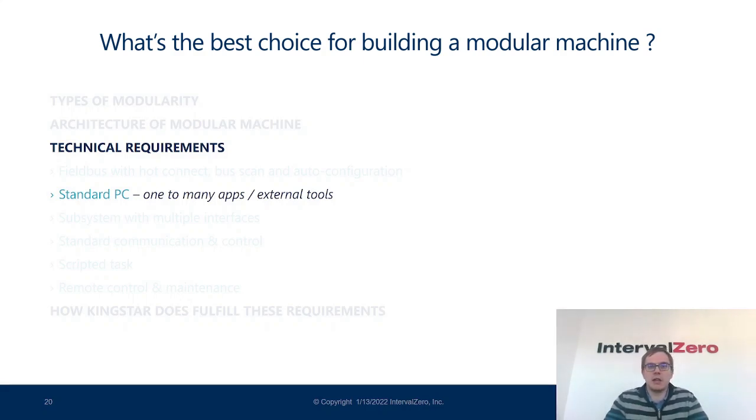And in this case, it is much more expensive in time and in price to build and have these PCs, these dedicated boards and dedicated ARM PCs built for your application, for your system. You have to select them, order them, and it's only worth it when there's enough volume. So when you do modular, you will have many different variations for one single application. So a standard PC becomes the simplest solution, what you save in time and usually in cost too.